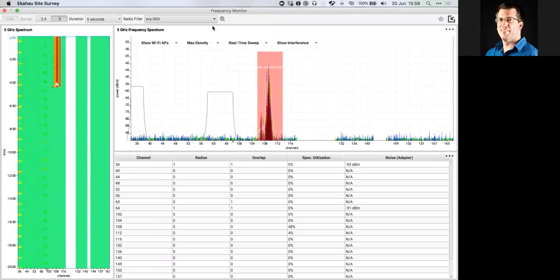And like you said, Nick, they're really, really short, sharp, powerful spikes. So think of this video transmitter, but shorter, but equally as dense in terms of highly utilizing that channel. And it's enough to drop the beacons from the point of view of a wireless device and effectively render that channel inaudible.